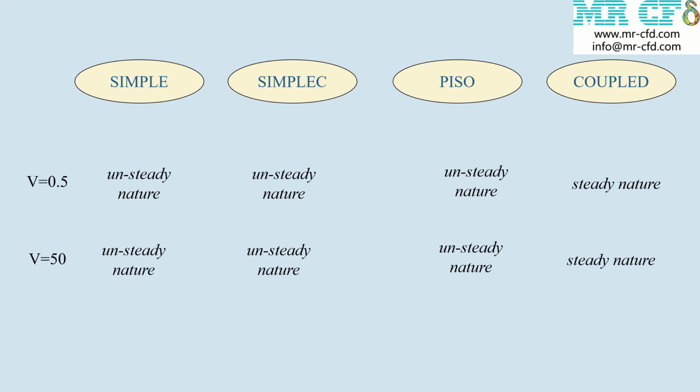This suggests that the steady coupled algorithm is less suited for unsteady simulations unless the unsteady form of equations, incorporating time derivatives, is employed. When used correctly for unsteady problems, the coupled approach can deliver highly accurate transient solutions.